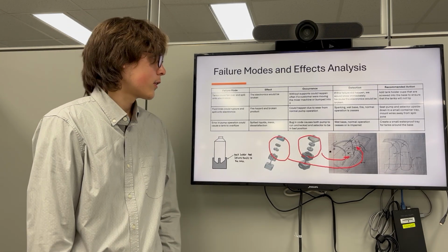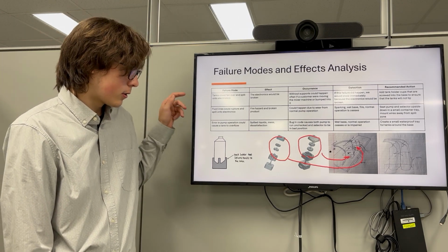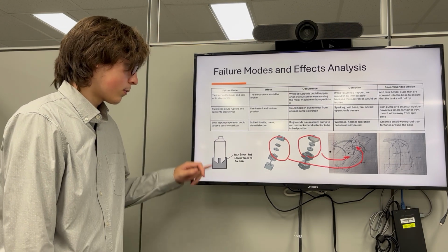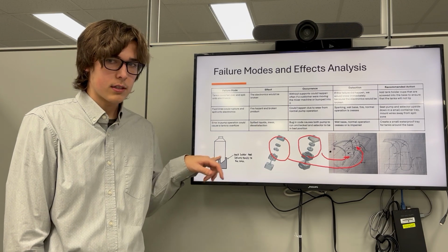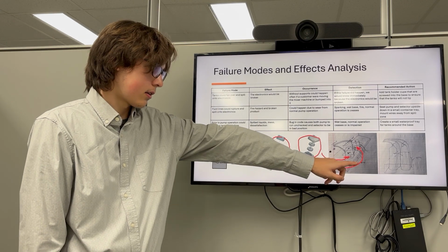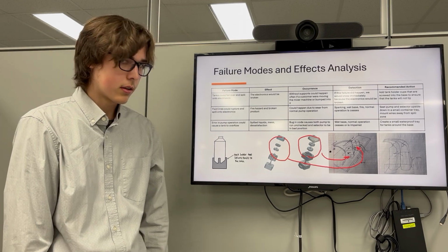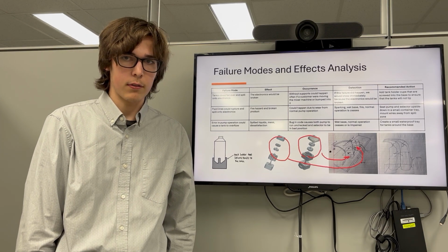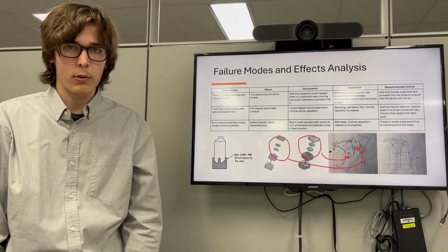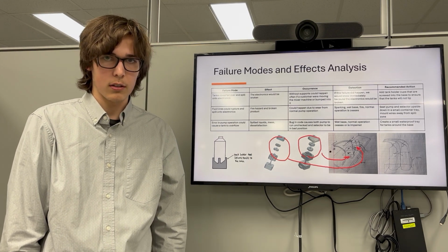We did a failure mode and effect analysis where 3 failure modes were identified and 3 solutions were identified for them too. One is a tank holder that secures the base of each tank so it's harder for them to spill. The other is a seated liquid collection tank for the pump and selector if any of the lines fail. And the last one is a liquid collection tray for the tanks if they get overfilled.